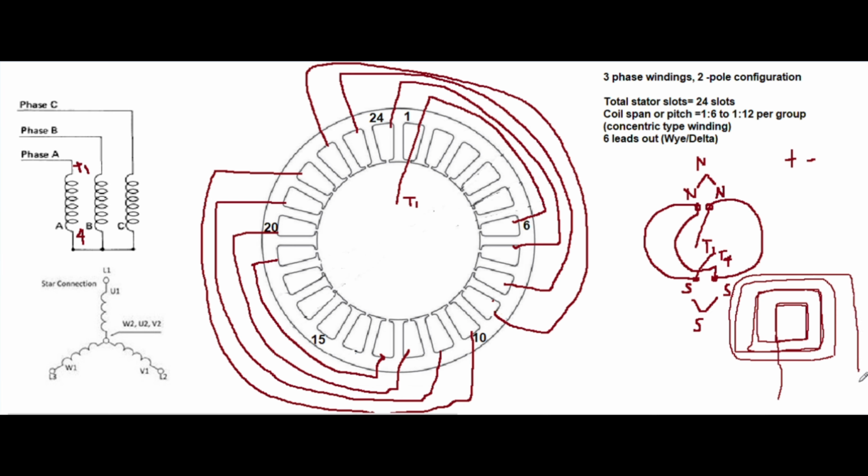You have the output here of the first group. 1, the output, so this one is the output. Slot number 9. If we're going to follow this pattern, this connection is inside, they're connected inside. We will go, and this will be north. These are all north here, north, north, north, all south here, north, south, series. It will be connected that way in series.